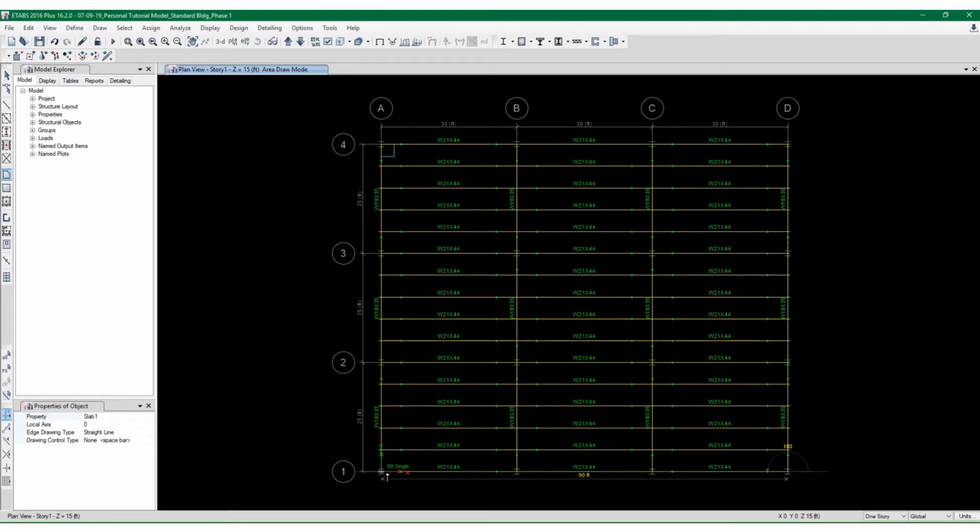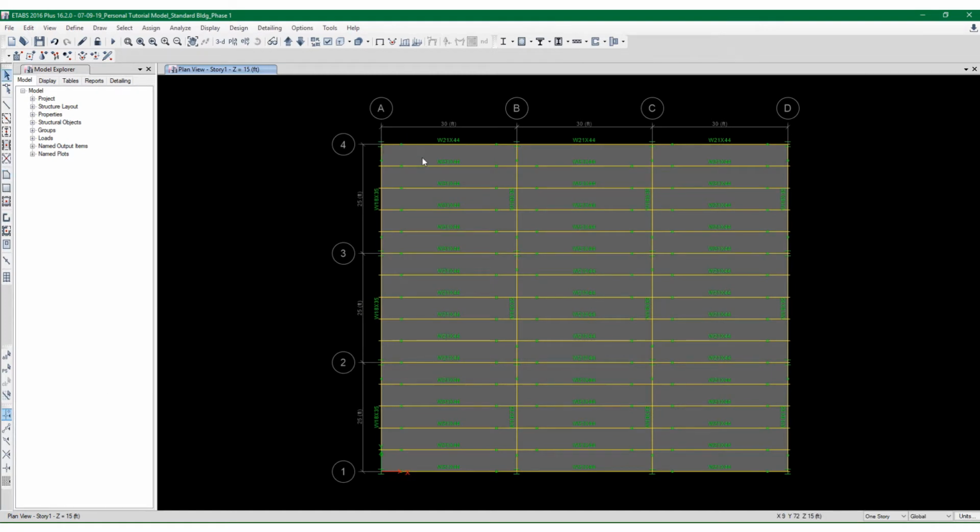So just move the mouse over and go to the point. You can see information that pops up next to the cursor. It says what point you're at. It's just kind of hard to see at the scale, but you're at grid point A1. Say OK. And then for the last point to close it up, you can either click C on your keyboard, or the final point, where you began. I like to click C because that typically does the job pretty well. Let's see. It's not doing it, so click the final point and it does it.